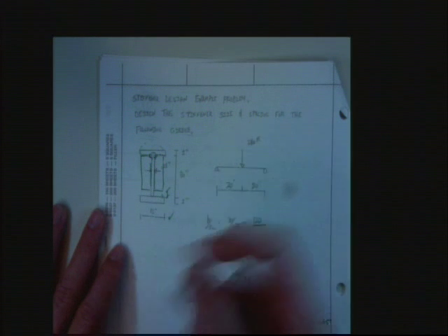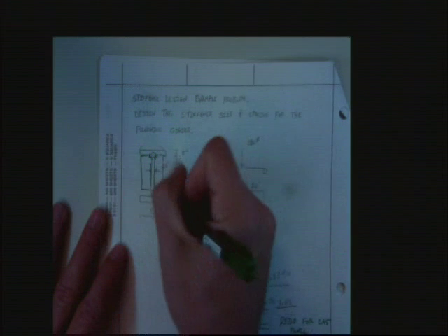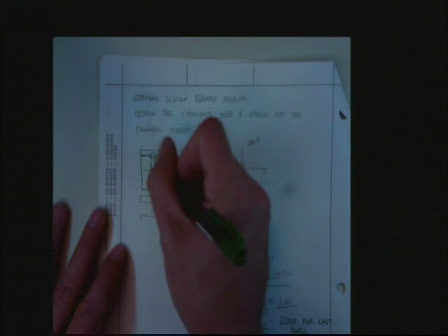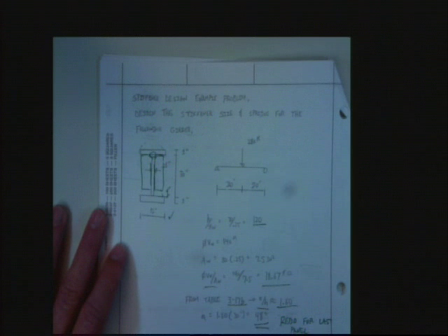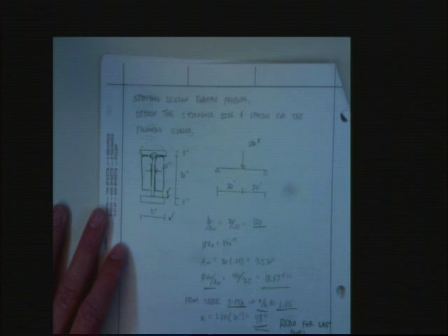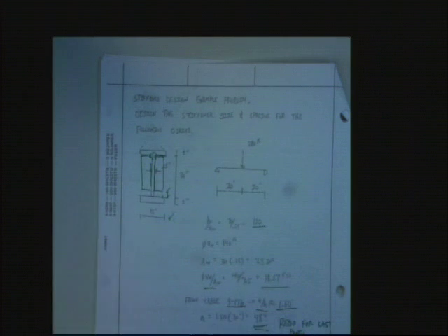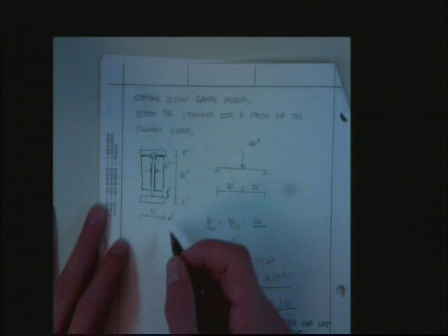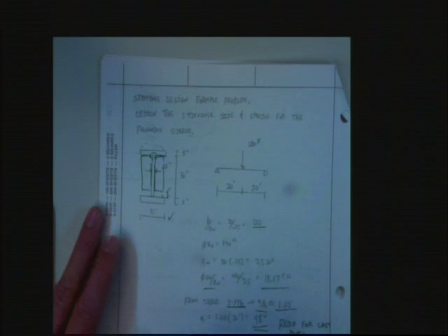What's commonly done then is I don't require it to be welded down there. It only bears. So you weld at the top, you weld at the bottom, and you let it bear on the bottom flange. Why wouldn't you weld at the bottom and let it bear on the top? You could do that too, since welding upside down is harder to do. But in the shop here, they'll flip the whole girder over. Shop welding. Right. Never mind. That's right. Do you increase the height of that? We're coming to it.